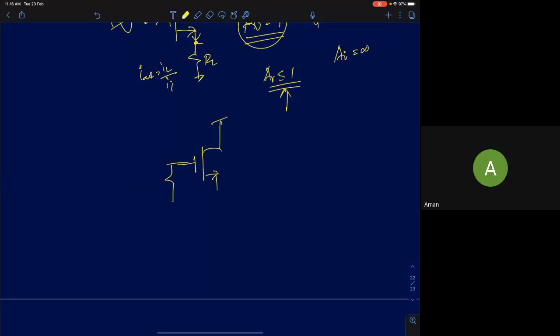In reality, probably some of you might have already done your lab assignments. We will have some bias resistance, which will be used for biasing. I'm drawing the small signal model here, so I have not shown the capacitor. Usually you might have some bias resistor, which will absorb some current from the source. It's not that the source will not provide any current at all. It will absorb some current from the source. This means there will be some power. So Vs times Is is the power drawn from the voltage source. That's something you will always do.